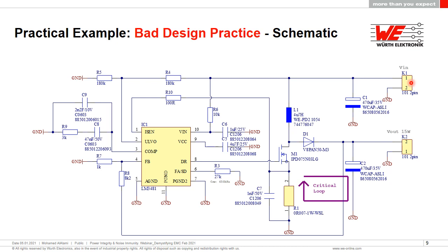It's a 15 watt power throughput. The switching frequency of the chipset is around 650 kilohertz, and it's a current mode control topology. It's non-synchronous, so you've just got a standard diode rectifier at the output. We've identified on the schematic the critical loop that we talked about before from a di/dt point of view. Naturally, the hot node is there.